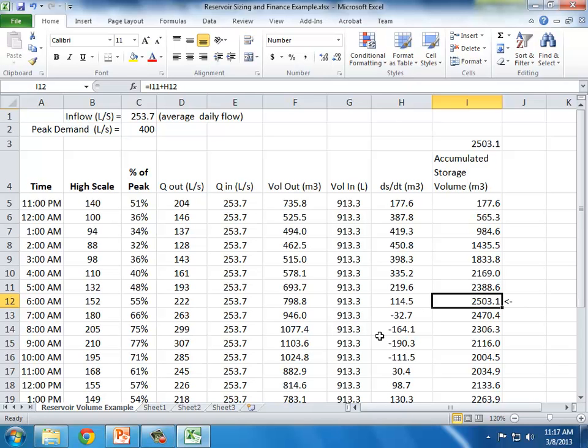But the treatment plant, the bugs and bacteria that break down waste and wastewater, they don't like these huge changes in flow rate and organic loadings. It's more efficient to have a steady waste stream being treated. And so flow equalization basins are also sized using the same approach of incremental volume balancing.